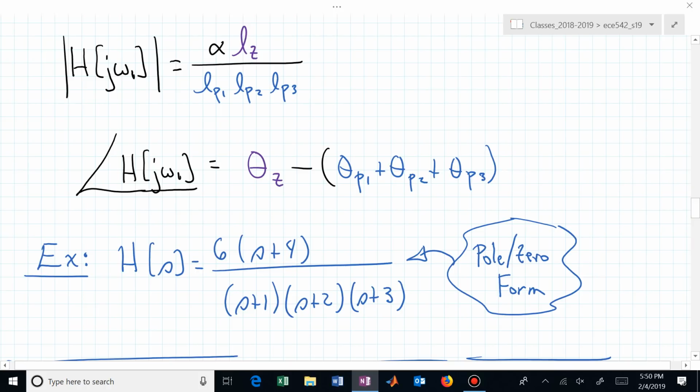And it has 3 poles rolling off before a 0 kicks in. And you should be able to sort of visualize or quickly sketch what a Bode plot for this might look like. Those poles and zeros are very close, so they're almost on top of each other, but you have an idea of how you could sketch the Bode plot for that transfer function.